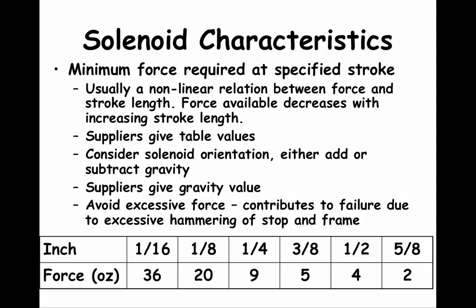Another thing to avoid when selecting solenoids is purchasing excess force. If the solenoid coil generates excess force, the continuous hammering of the stop and frame leads to premature failure.